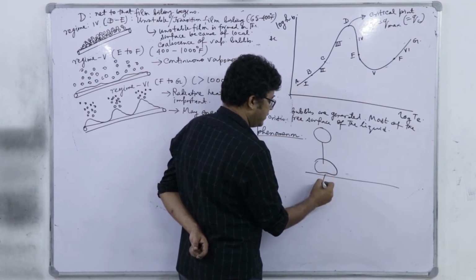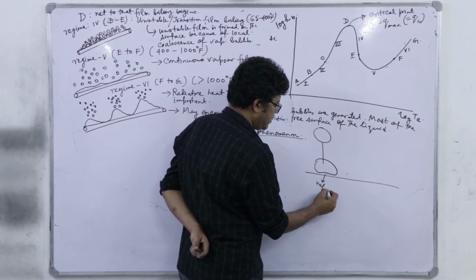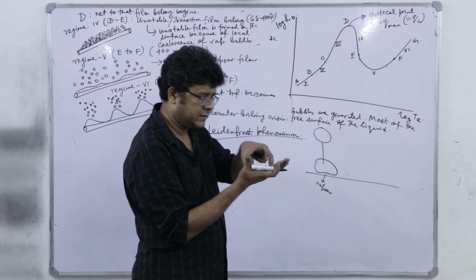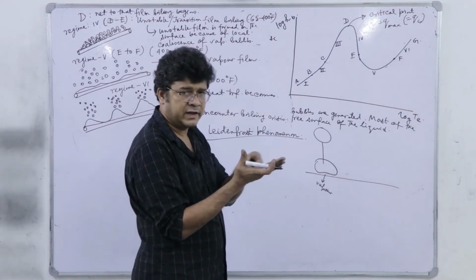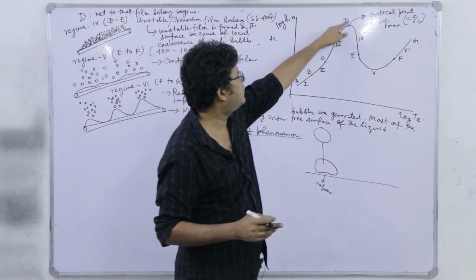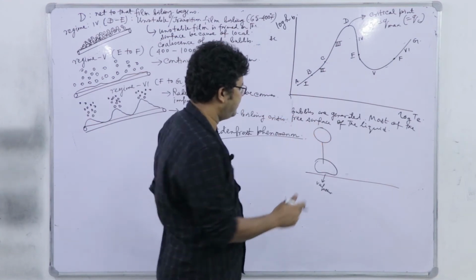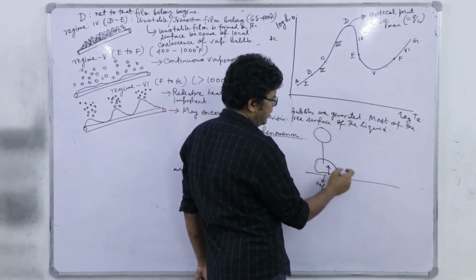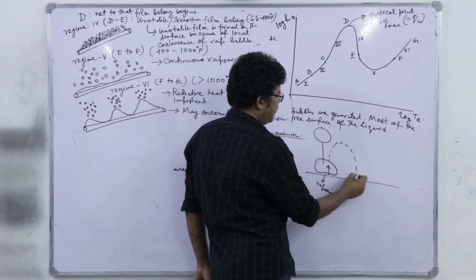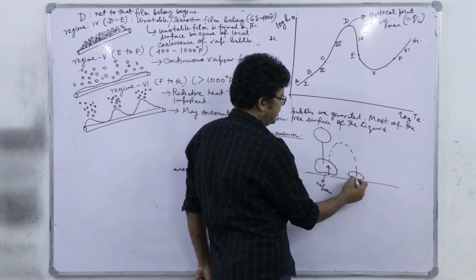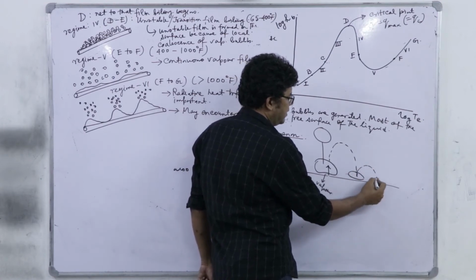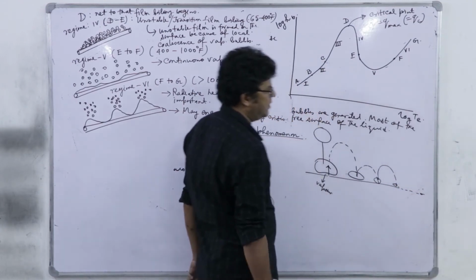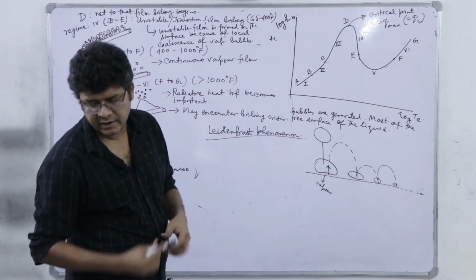There will be generation of vapor, right. The drop will sit on the surface, and there will be nucleation immediately, and there will be a switch from nucleation to film. So, there will be a film, and the film has got a high pressure. So, it will eject the drop again from the surface. So, it will move up like this, and again its size decreases, the same phenomenon is repeated, right. So, it will go on doing this before it finally evaporates. So, this is called the Leidenfrost phenomena.